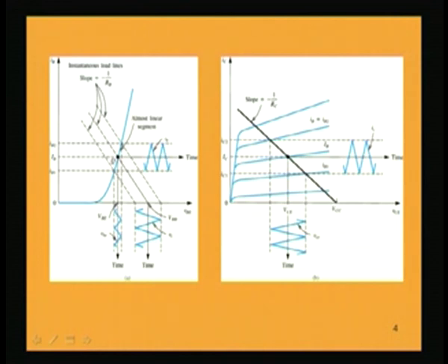If we consider the DC V_BE, then when the small signal is in the positive half cycle, we have an increment of the base to emitter voltage. Initially this is the DC V_BE, so it will be rising in the positive half cycle and reducing in the negative half cycle.